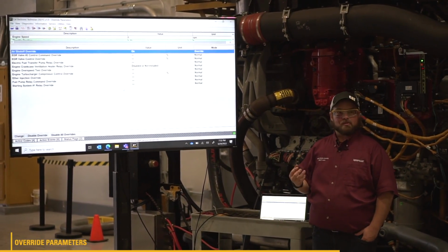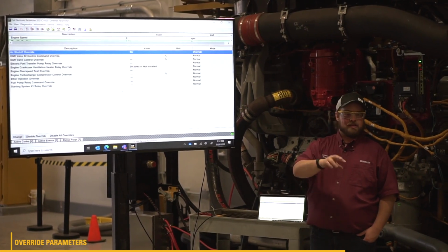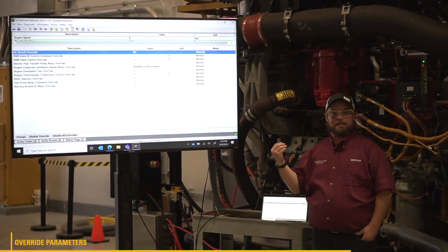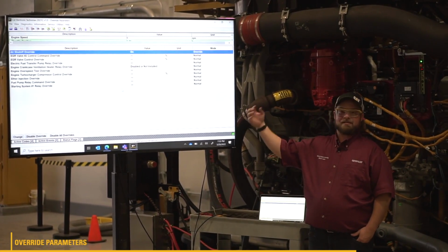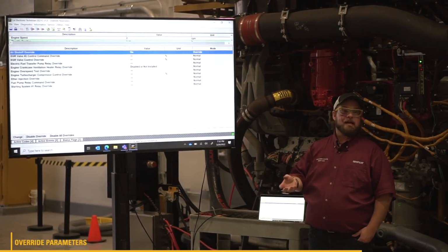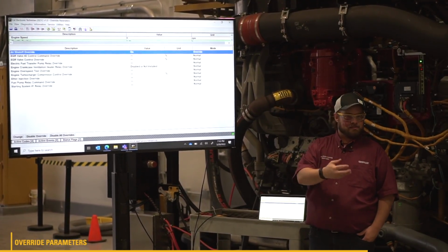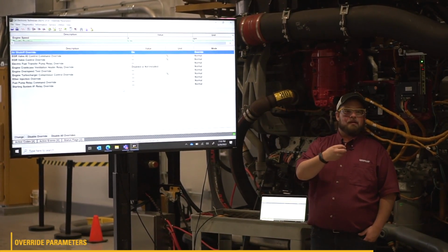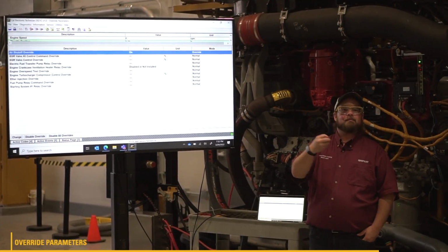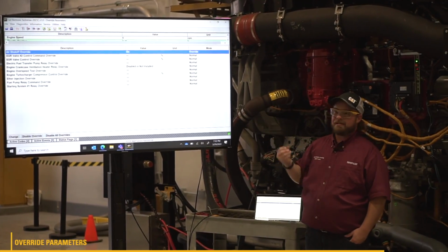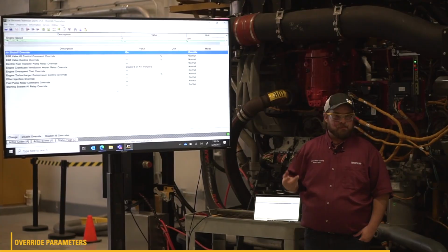So if I were troubleshooting this, again, if I had a dash 5, I'd have made a short circuit in that harness, ran this test, and then see for my code to change, and vice versa. If I'm dealing with the dash 6 code, then that's a short circuit, I would make an open circuit, activate the output this way, and see if my code flips.